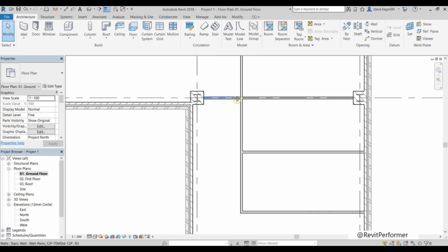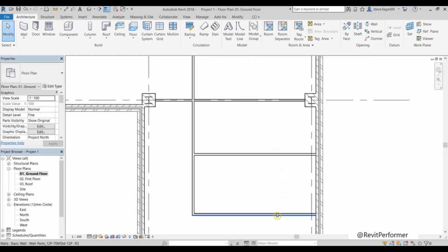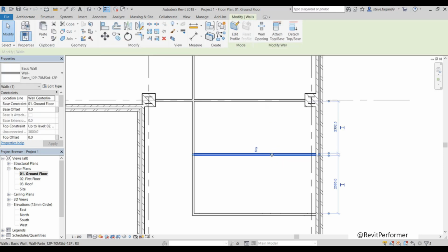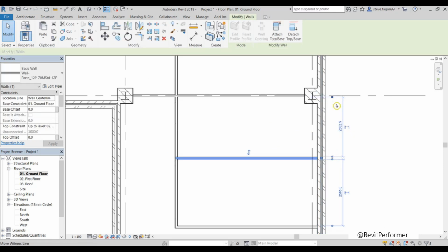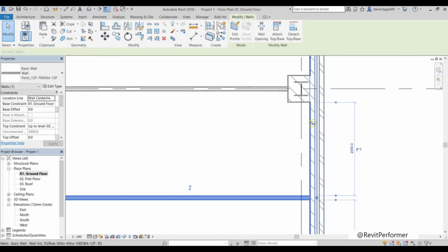So this wall here is at the center point, same here. And so these walls here are 2000 down. So if I select my middle wall, you can see my temporary dimension is 2302.5. If your temporary dimension is snapping to the column like so, we can adjust its position. So with that blue grip, I'll click, drag, and move it up to the face of the plasterboard and let go. Now I can change the text to 2000.